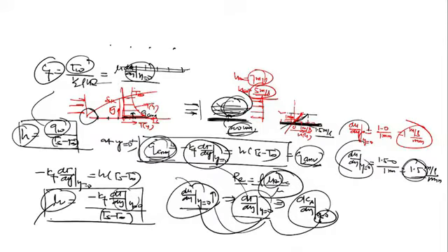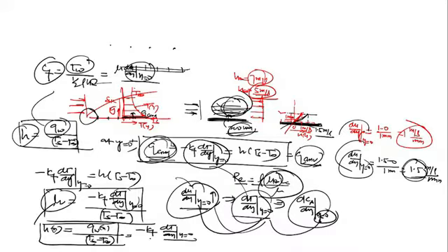And that's why this is called the local heat transfer coefficient, h_x. Why is it h_x? Because q_w, the wall heat flux, is a function of x. Do you remember any similarity? And q_w is nothing but the wall heat flux, and at the wall heat transfer is by conduction: minus k_f into dT upon dy at y equal to 0, upon (Ts minus T infinity).